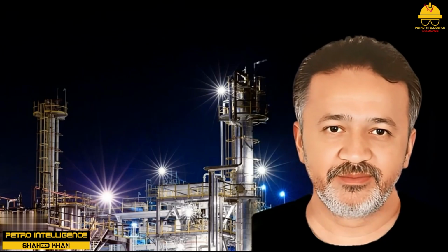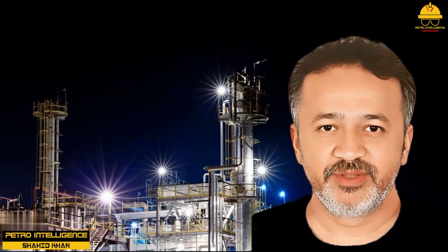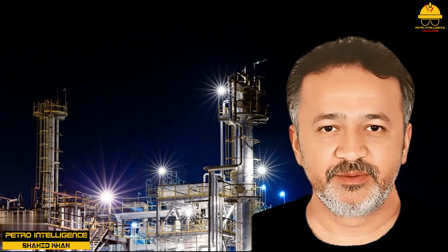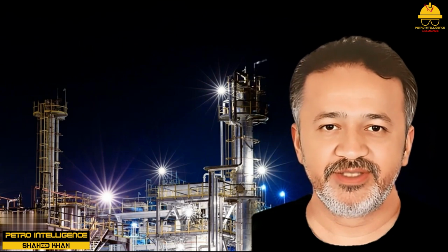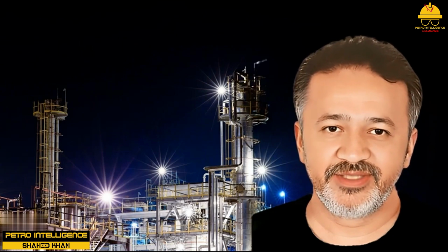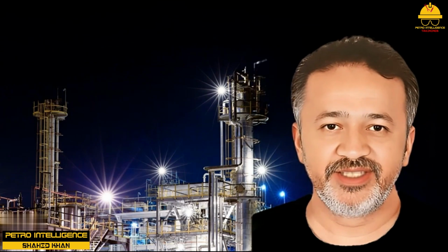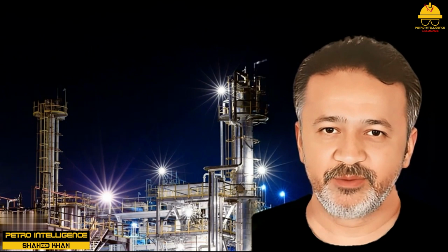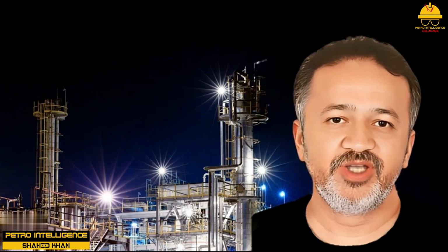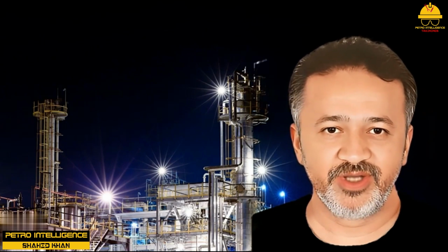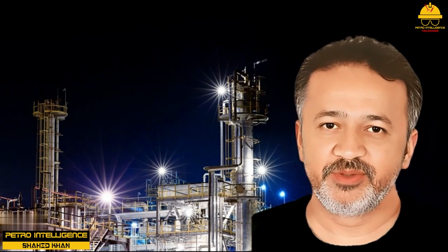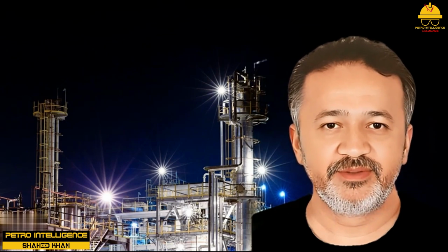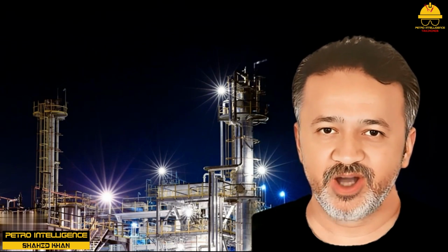Material balance. Material balancing is a method used by technicians to determine the exact amount of reactants needed to produce the specified products when two or more substances are combined in a chemical process. Reactants must be mixed in the proper proportions to avoid waste. Material balancing provides an operator with the correct ratio. A balanced equation is a chemical equation in which the sum of the reactants, atoms, equals the sum of the products, atoms.